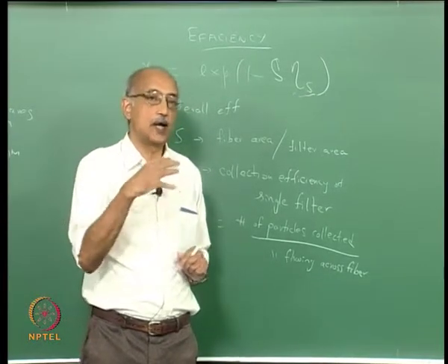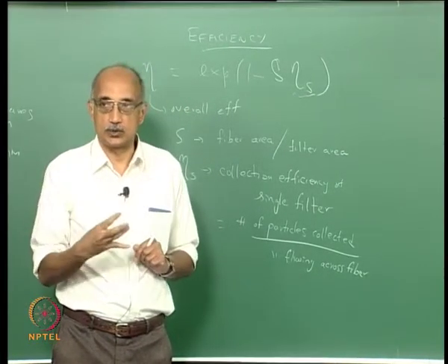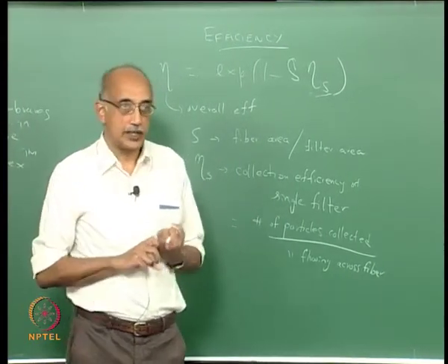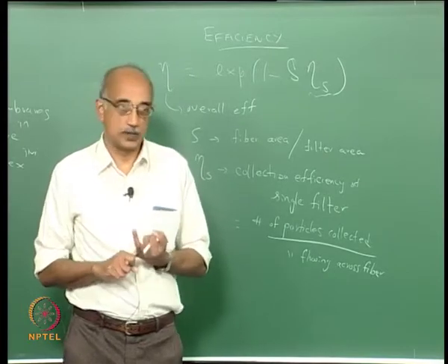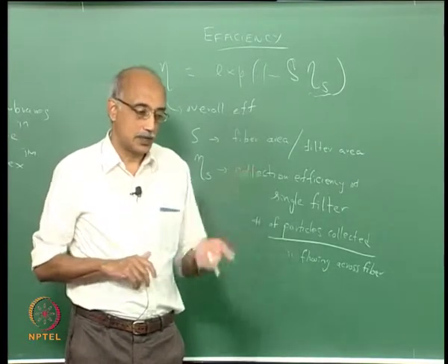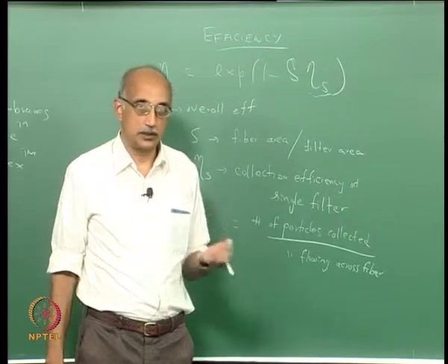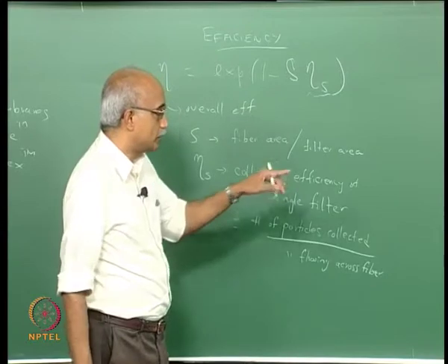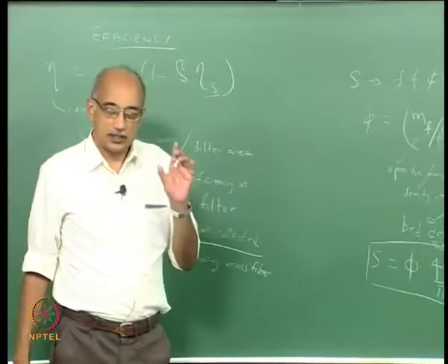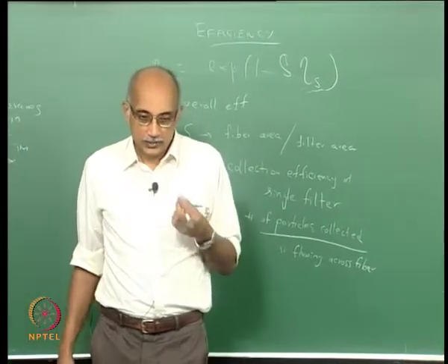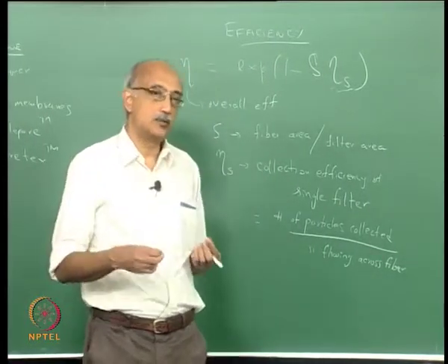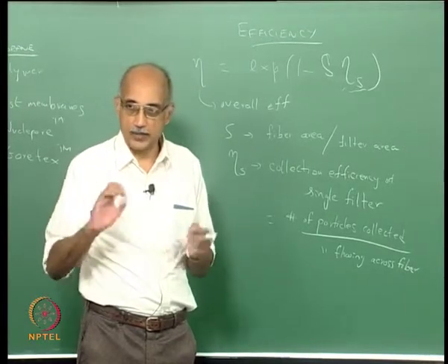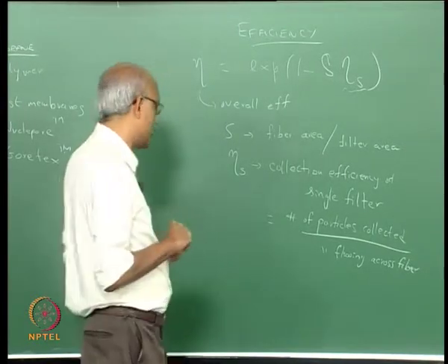Now, here we go back to the material that we have covered earlier in this course. This basically depends on transport properties of particles as well as their adhesion properties to surfaces, in this case the surface of the fiber that the particle is flowing across. Before we do that, the other parameter that we are interested in is the pressure drop. As you know, in filtration technology, virtually anything you do to improve efficiency also results in a higher pressure drop, and you always have to balance between the two.